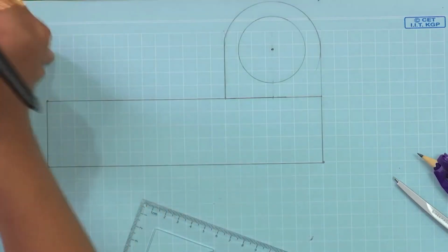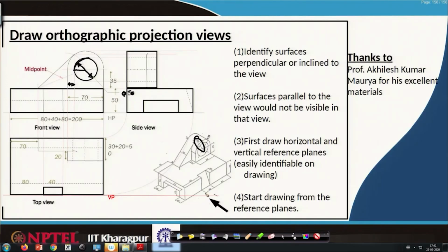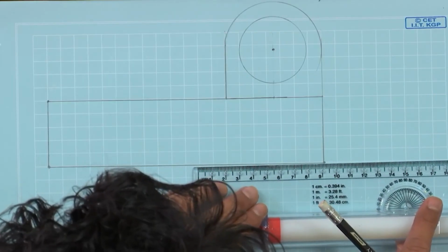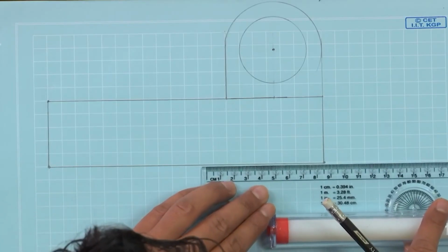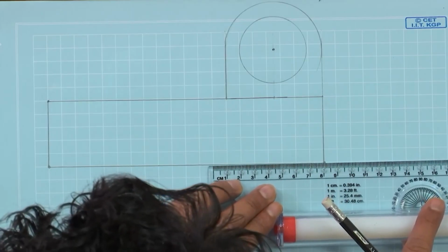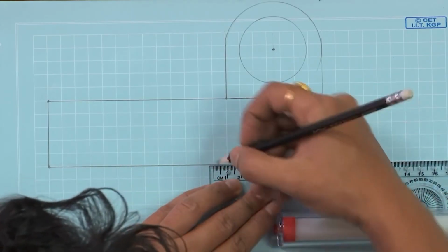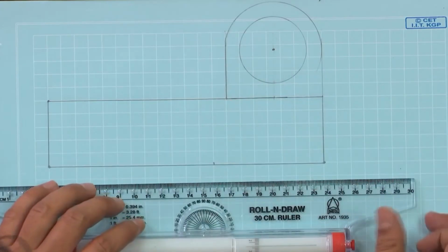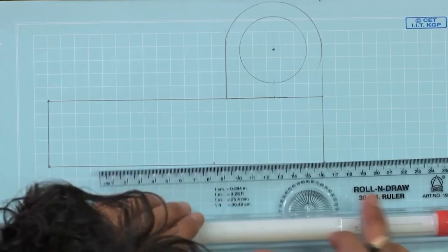After that, we have the object of something 40 mm, and we have to construct a slot starting at an 80 mm distance. So, locate 80 mm from one of the edges on the scale, this is the edge, and all the way to 40 mm we have to locate a slot.